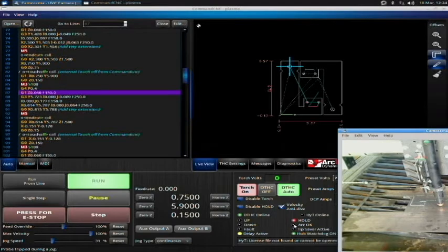It comes from your plasma. It tells the machine, okay, the arc is thrown, let's start a cut. Because I have the torch height control on, it is waiting for the arc OK. If I had the torch height control off, it would not wait for the arc OK. It would just simply go through the motion and attempt to fire on the next cut.